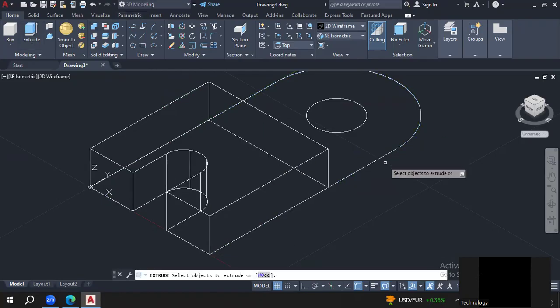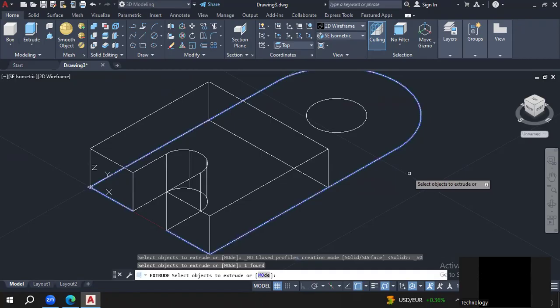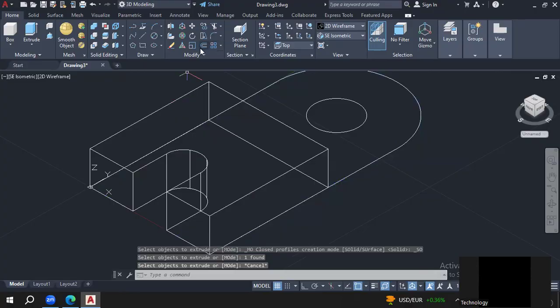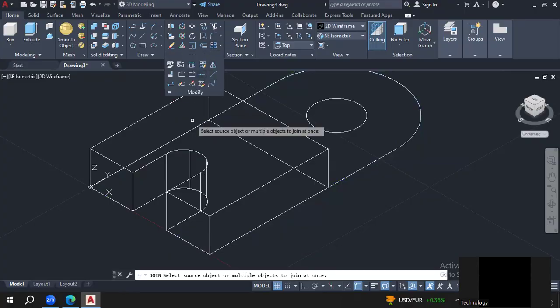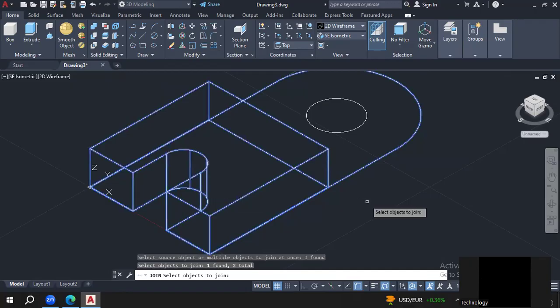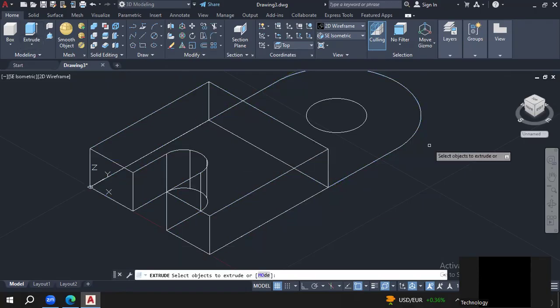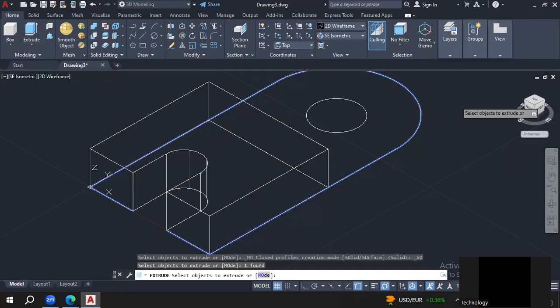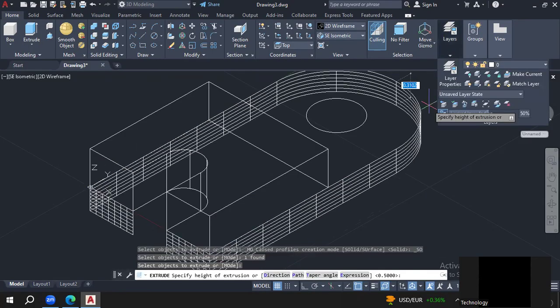And now extrude it. Okay, we are missing one thing. It will extrude out the whole part. Okay, it doesn't matter. We can further complete it and then we will use the subtraction command. So this and this, just go for it. Extrude to a height of 1.